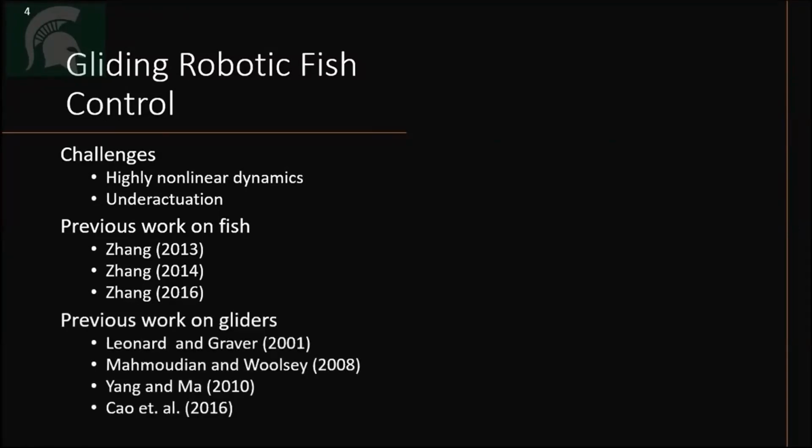Previous work in underwater glider control can also be applied to the robotic fish, but most of this control literature focuses on control designs to reach desired pitch angle, velocity, depth, or steady state gliding paths. 3D motion control is scarce, likely because gliders usually operate in the open ocean and only need to be concerned with the planar gliding profiles. However, this robot is capable of maneuvering through smaller, more complex environments, making fine-grained trajectory tracking more relevant.